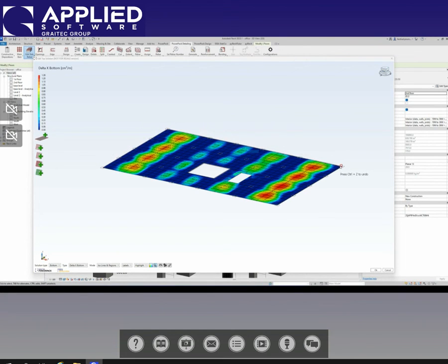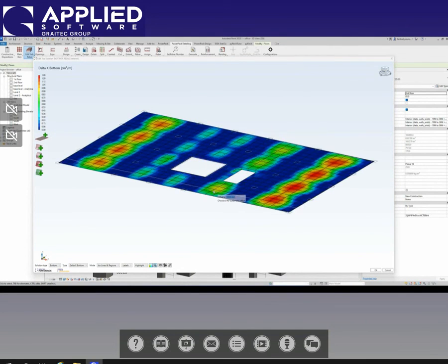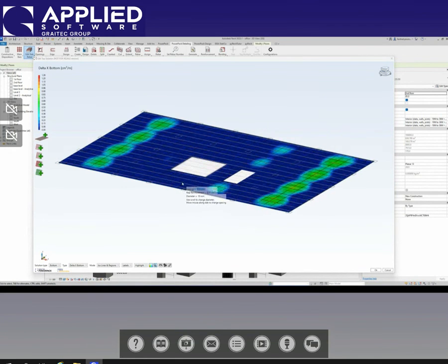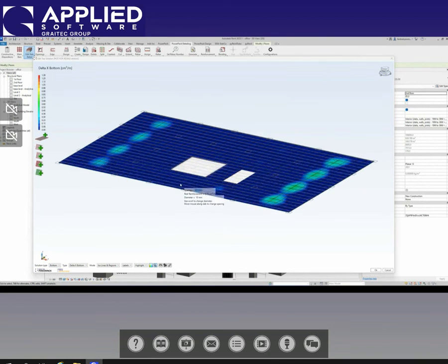There you go. You just need to click on the corners. And now I have the control to put my rebars. And this is going to be dynamic fully. So for example, I can start my first rebar, let's say from 500 millimeters. And now I can start by adding or changing the distancing based on the rebar area that I require. And as you see, it's fully dynamic.